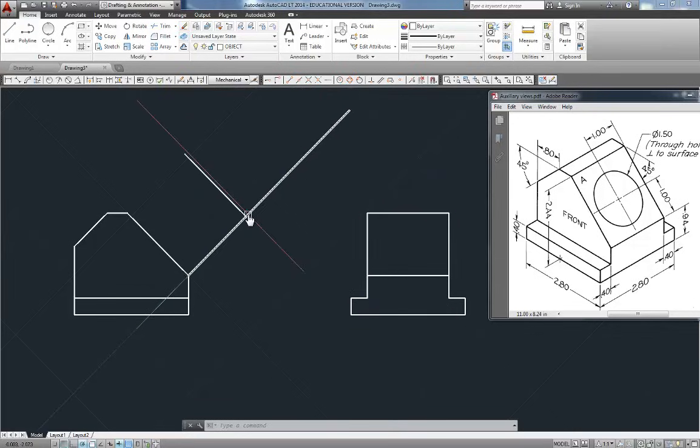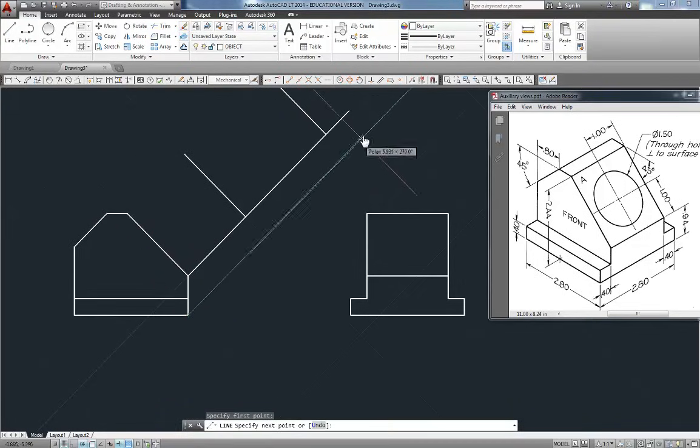It will dramatically change the depth of your part. So everything for depth has to just be the offset command. You cannot do any kind of projection to get depths. So again, we know this part is 2.8 deep, so I'm going to offset 2.8 and get the depth of that part. All right? Well, actually in this part, this is the very front corner when I'm in this view, so I'm going to pull that edge up there.